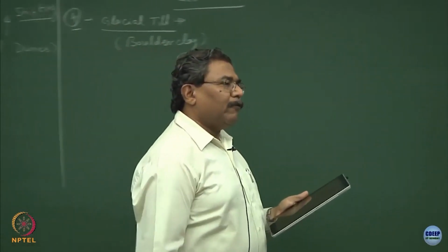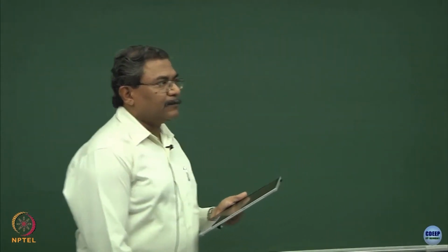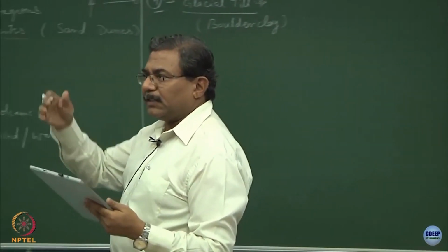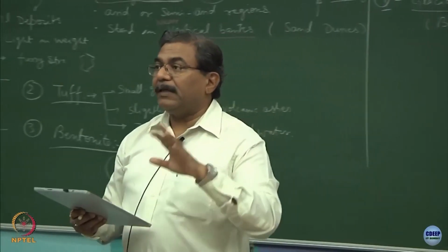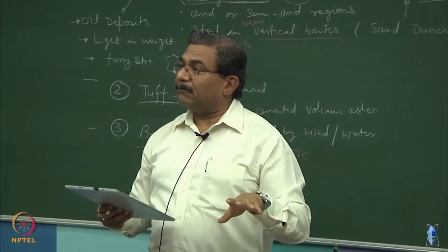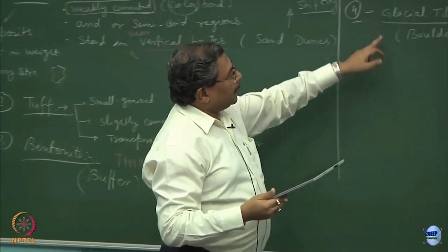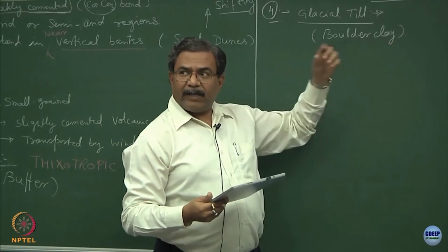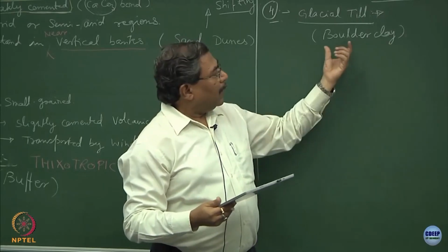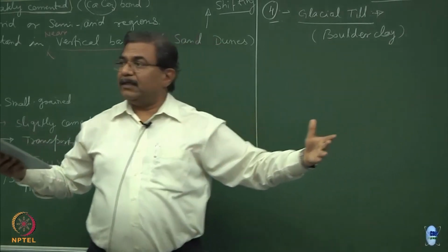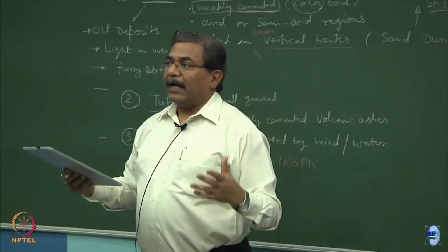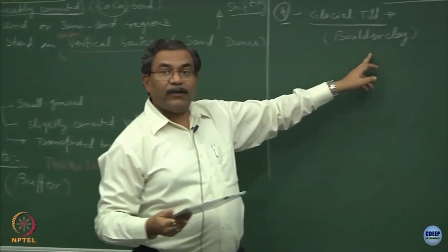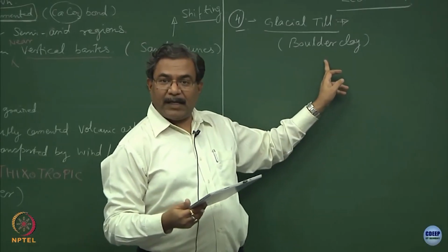Those of you who come from Himachal Pradesh in particular, or maybe the upper or lower reaches of the Himalayas, you will realize that the big difficulty there is to lay the foundations. Why? Because these types of materials have a combination of a clay fraction, which is very fine particles, and boulders which are very big in size, clear. So, I can't sit on a boulder; when an earthquake comes, these types of deposits are going to get destabilized very fast.